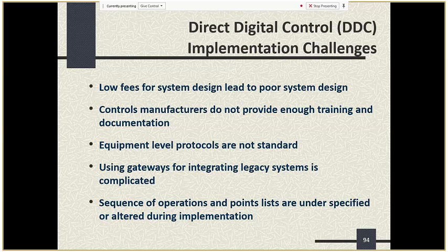But in my experience, one of the things that really makes energy management control systems work properly is having really good training, really good support from the manufacturer of the control system, good naming conventions, and doing a good job of integrating it with the field equipment. And if all those things work right, then you get a much more valuable system for control and optimization.